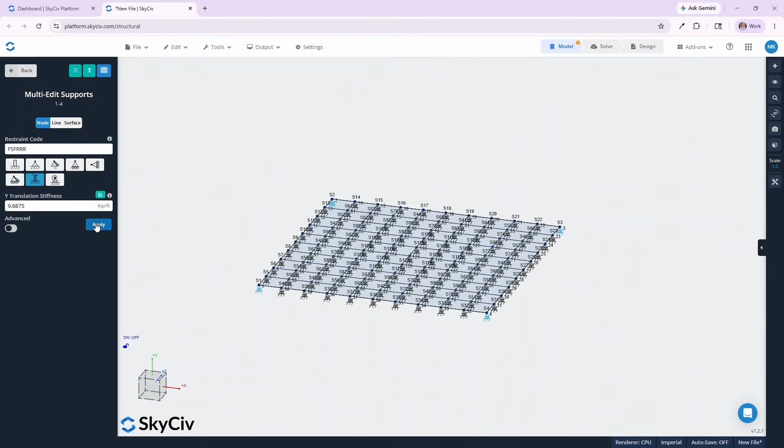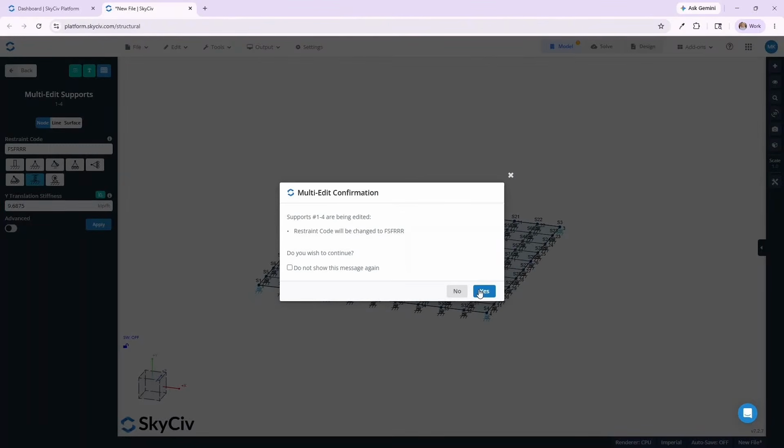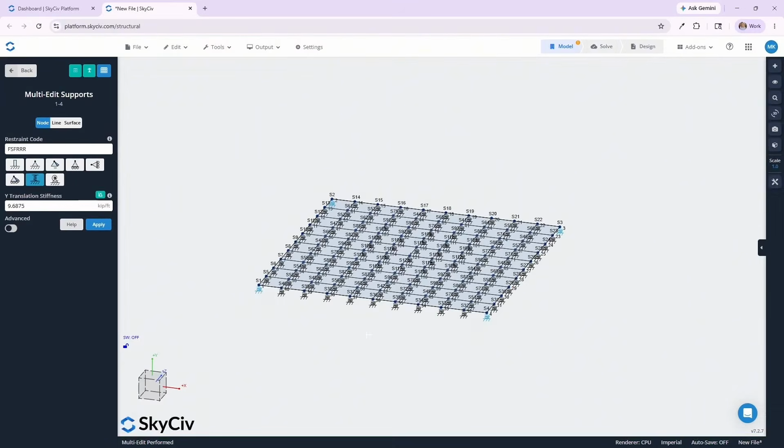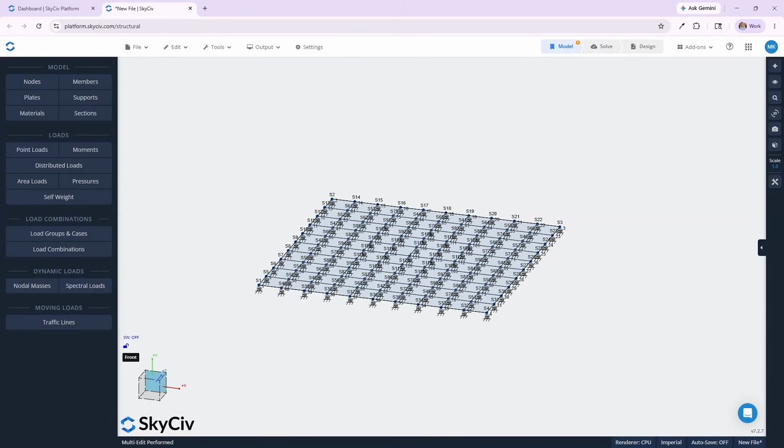If you were analyzing lateral slab behavior, you could represent horizontal soil resistance by using spring restraints in the lateral direction instead of fixed restraints. Those stiffness values would also come from geotechnical input or engineering judgment.